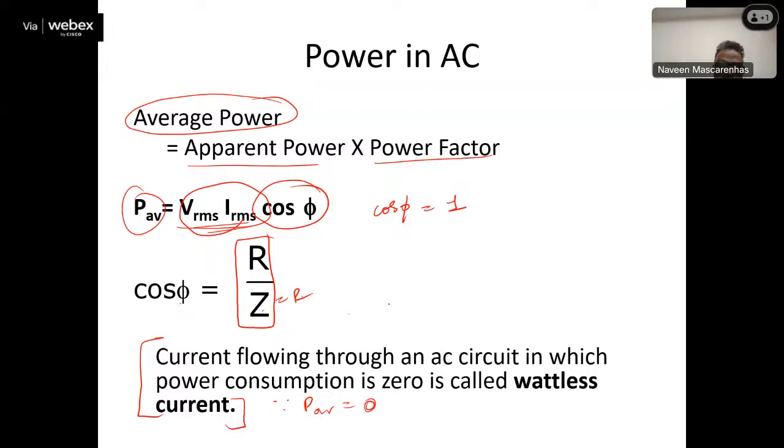Choke is a high inductance coil. Now, why are we using a choke in AC at home? To restrict AC current, because it dissipates less power. Because it has got resistance. Definitely no coil is there without resistance, but the resistance is small. So a coil is always preferred when it is AC to restrict current, because it is not only a restriction of current, it also consumes less power. The average power consumed by the coil over the entire cycle is 0.